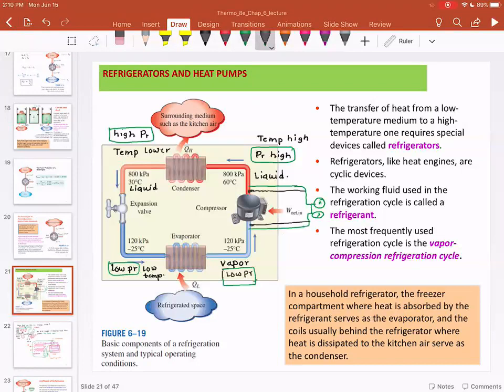What do you need to check? So what are the typical issues when the cooling is inadequate? When the cooling is inadequate, that means the pressure on the high side is not high enough, or pressure on the low side is not low enough. If there is a refrigerant leakage, then there is a loss of pressure. The compressor would lose pressure if the refrigerant is low.